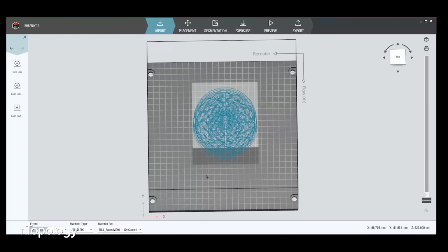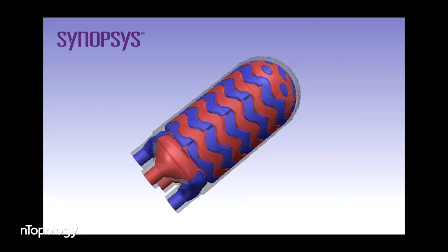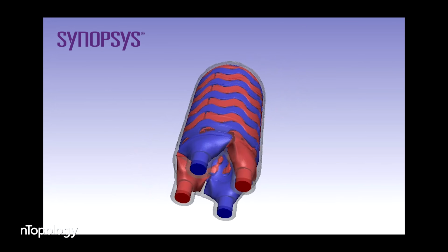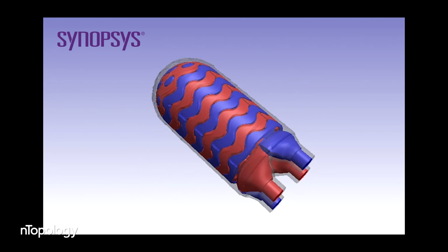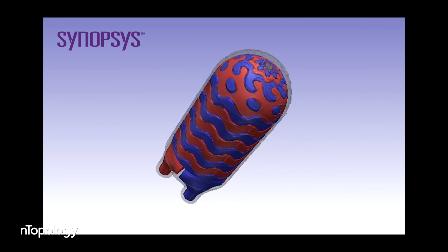2, slices. Slices were output to EOS for manufacturing 3D printing. 3, surface mesh. Surface mesh was sent to Synopsys for as-built validation. 4, a BREP. BREP was output back into CAD for integration with the bigger assembly. And then 5, an nTop file. The nTop file and any other associated files were stored in PLM for data storage and audit and any updating and change requirements. Because inevitably, there's going to be changes.